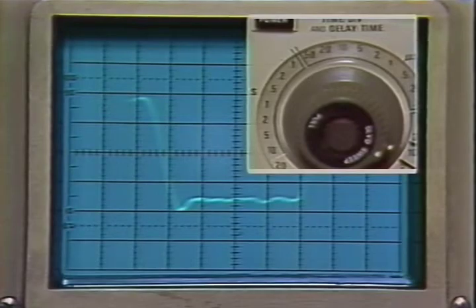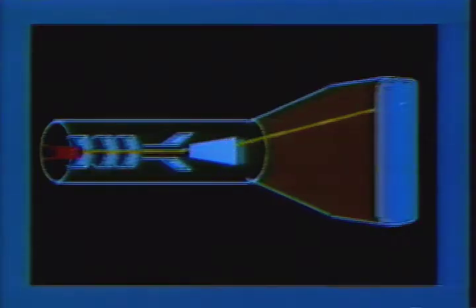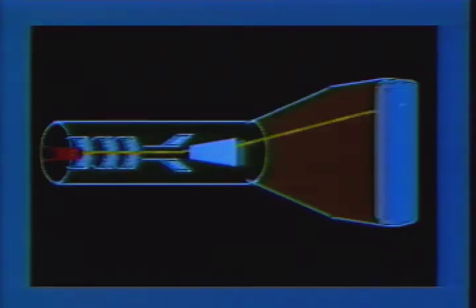So, why not supply more electrons in each sweep? There are trade-offs between beam size, current, high voltage, deflection characteristics, and other factors that limit the number and power of the electrons we can supply in the scanning beam. In a high-speed scope, these factors are already optimized for trace brightness. But there is another way to supply more electrons.